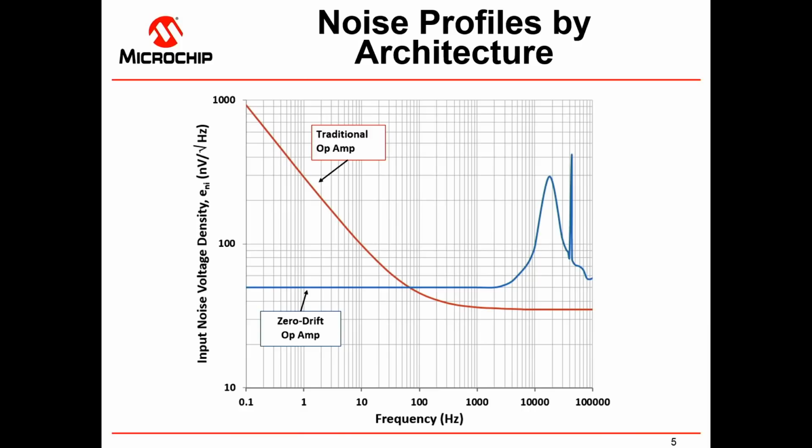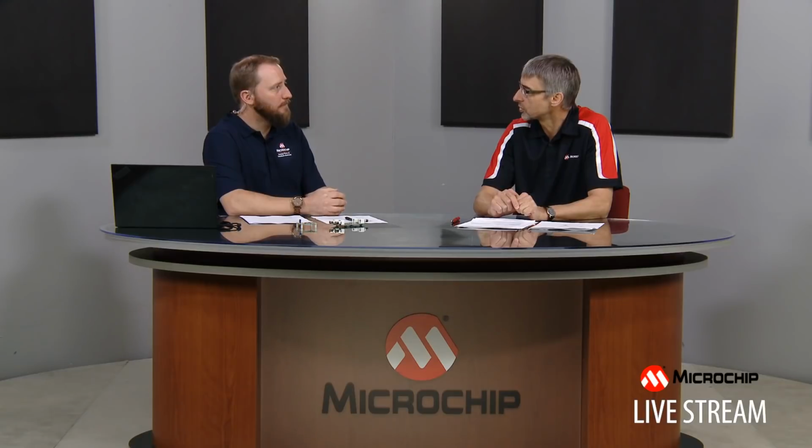So as a first order, 1/f noise is considered a slow moving signal. And since we are correcting at a rate of, let's say, every 100 microseconds or so, which is fairly quick, 1/f noise falls into that region of correction, and that's why 1/f noise can be very beautifully corrected for. And then you have the noise as a flatband noise in that region.